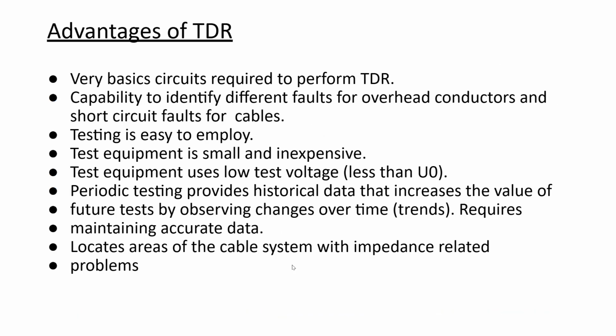So what are the advantages of TDR, the time domain reflectometry? Very basic circuits are required to perform TDR. You know how simple it is: sending a waveform, sending a pulse and then capturing it, and then we have to study the various distances, only various time scale, and then convert it into distances.